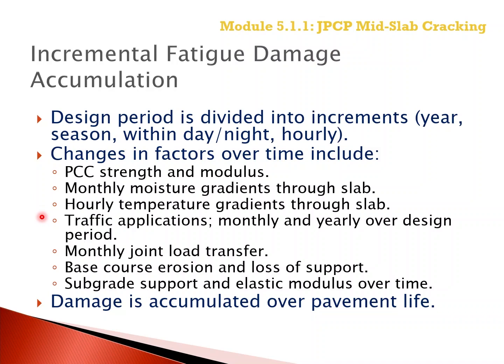The number of axle load applications also increase over time, and the different types of trucks do have different axle and tire geometries. The base layer can erode at different points of time, and the base PCC slab interface can degrade over time, which has an impact on the tensile stress at the top and bottom of the PCC slab.